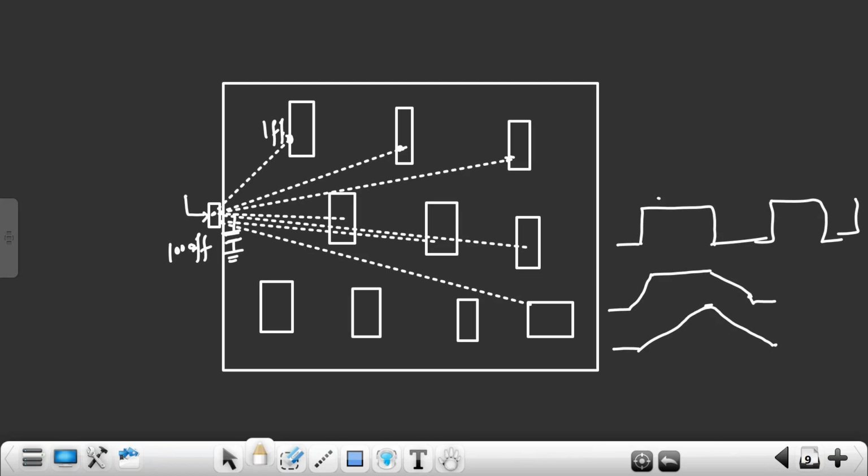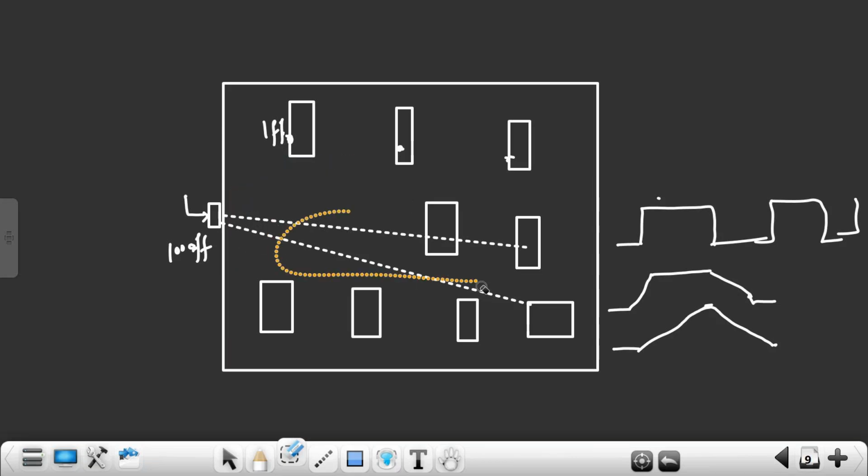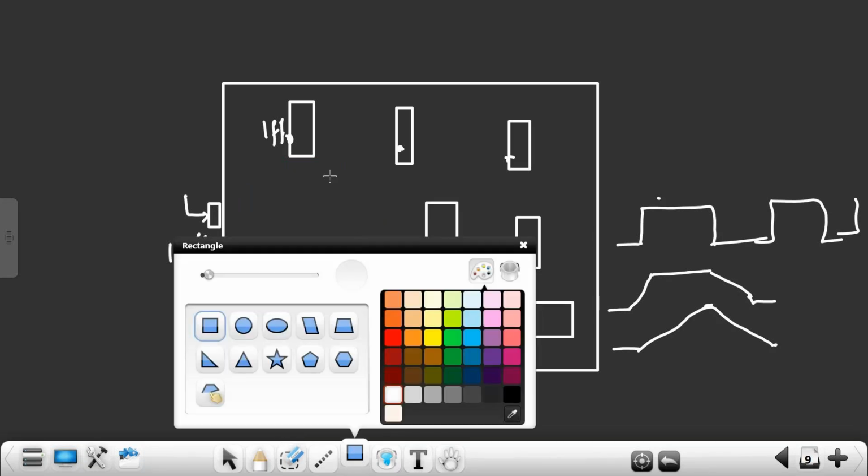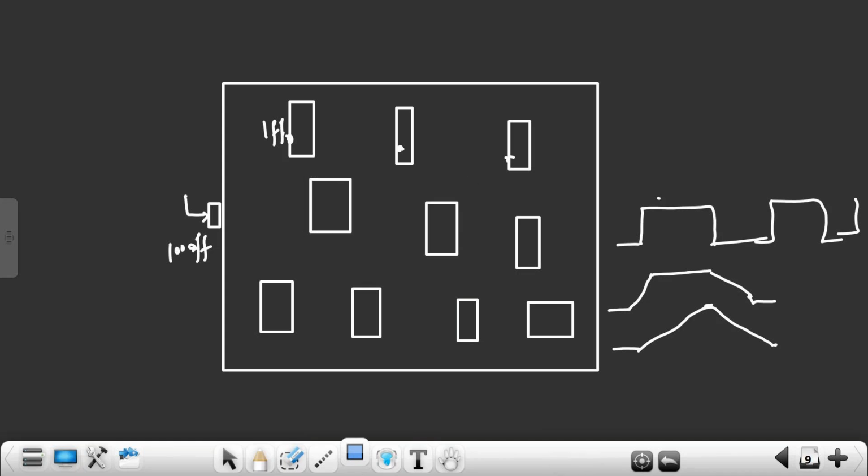So then what we do is we will start reducing the load on the clock port by building the clock tree. So how do you reduce the load? If I tell the principal to go and give one piece of information to the college today, that tomorrow is a holiday, how many hours will it take? What will he do? He will send all the information to the HODs. HODs will send to class teachers. Class teachers will send to what? The students, the ultimate load. The load is reduced. The information is also passed very fast. Similarly, here also, we have anchoring buffers first.